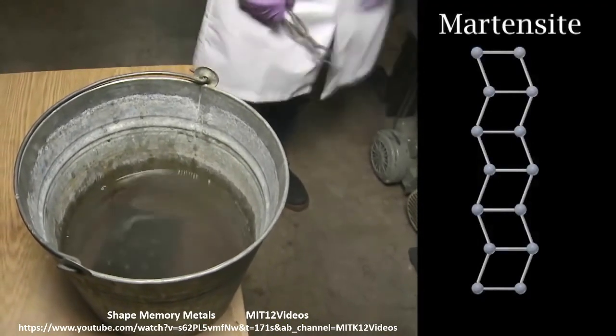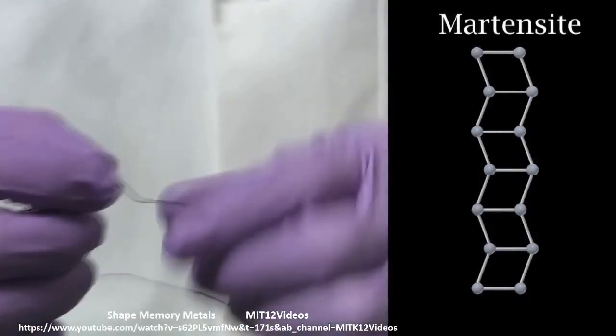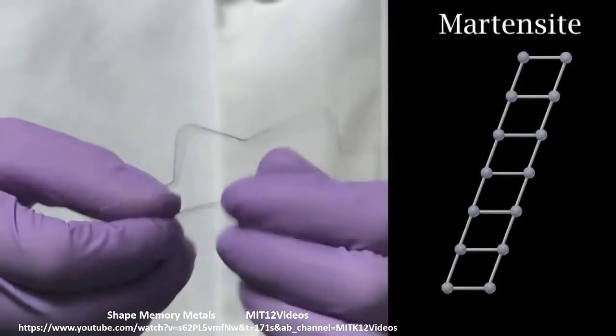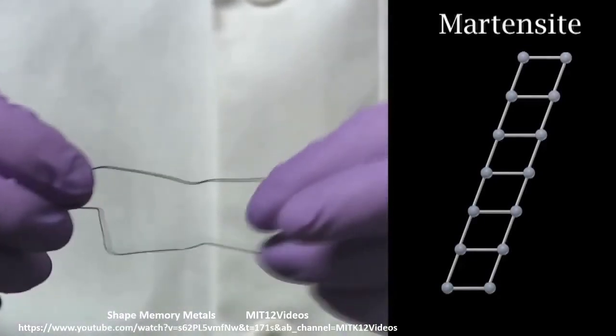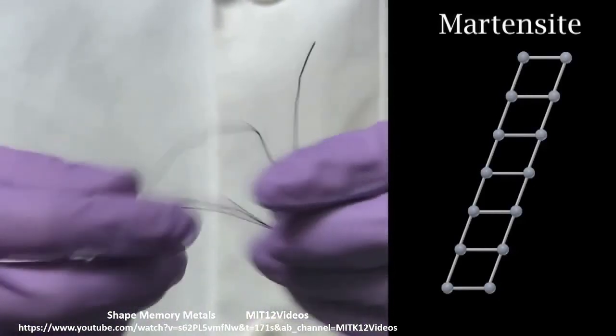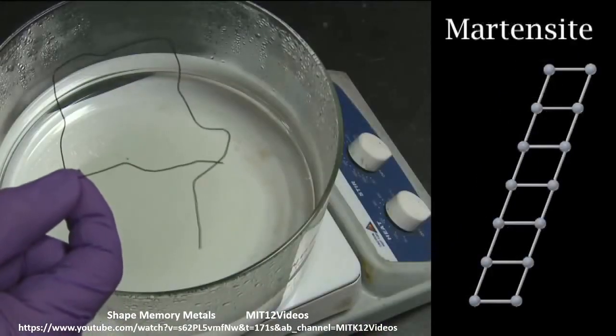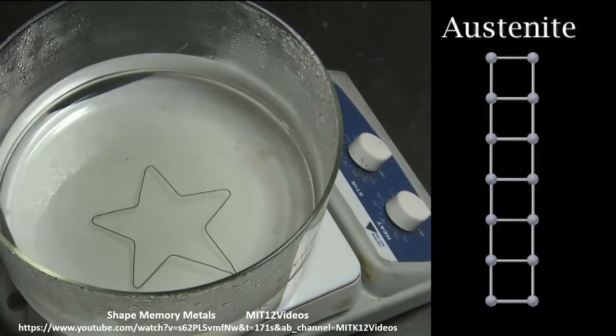twinned martensite phase. Now it's nice and cool, and taking this shape memory alloy and bending it around, remember, it's a physical change, but it's not a phase change. We're moving it into the detwinned martensite stage. So it's getting detwinned right here. And I think the most interesting thing about this is right here. It's detwinned. We put it in some hot water and bam, it turns back into austenite. I think that's really cool, and you can take it out. It will go back into the twinned martensite, and then you can move it around again.